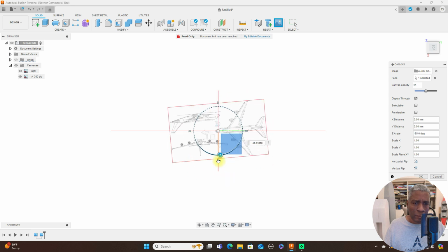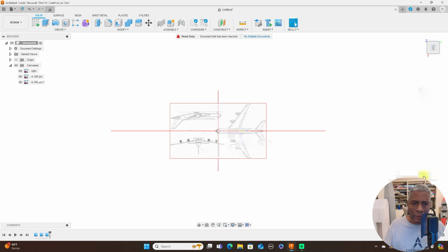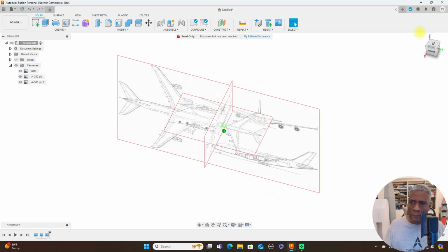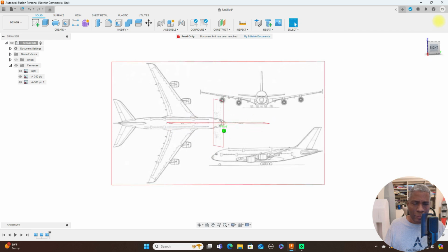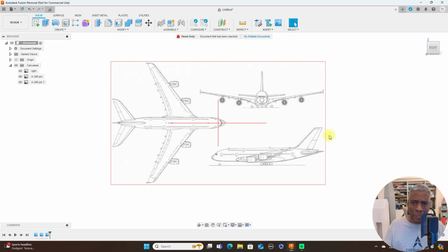And all the planes on my site, this is how I did them. And click OK. Now we have our 3 pictures in here. We have the side, front, and top view. And if you have a back view to put in, that's fine also, or bottom also. And then what I normally do is go over here and label these as front and top also.